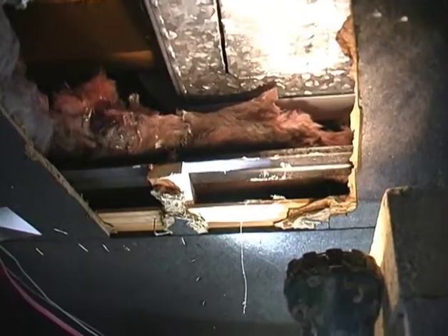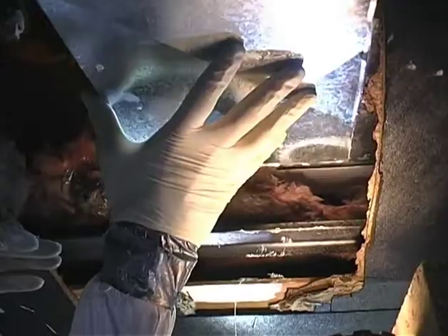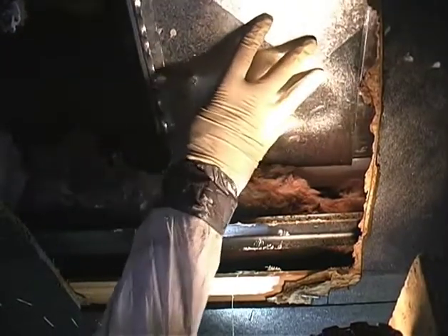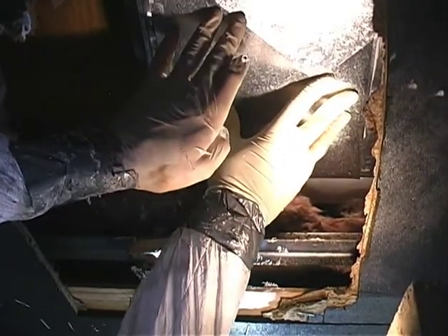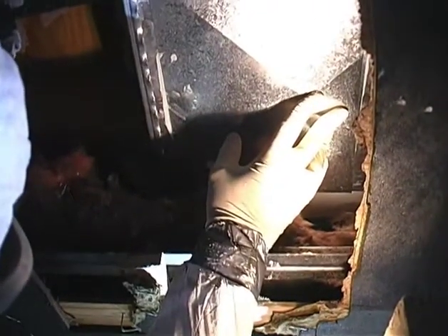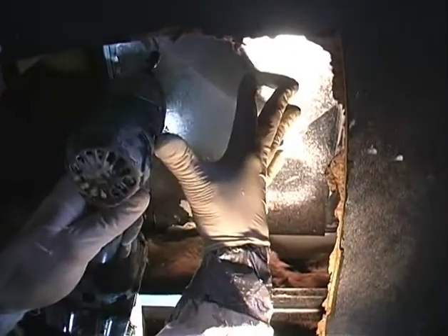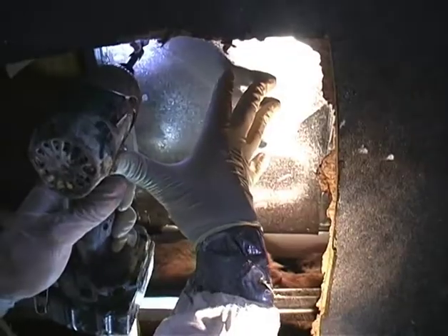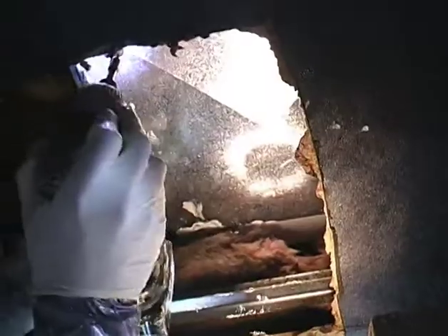It can be quite a messy job, so he's actually got several layers of gloves on, so he can take one glove off that has mastic on it and have a clean hand to operate his drill. He's placed some screws up on the cinder block there, so he has them readily accessible, and now he's going to attach the patch to the lower part of the trunk line.